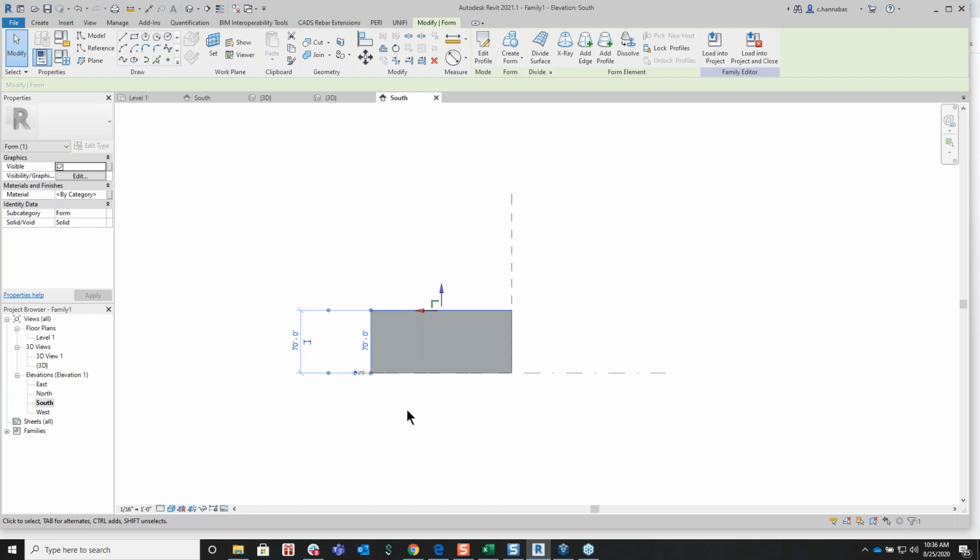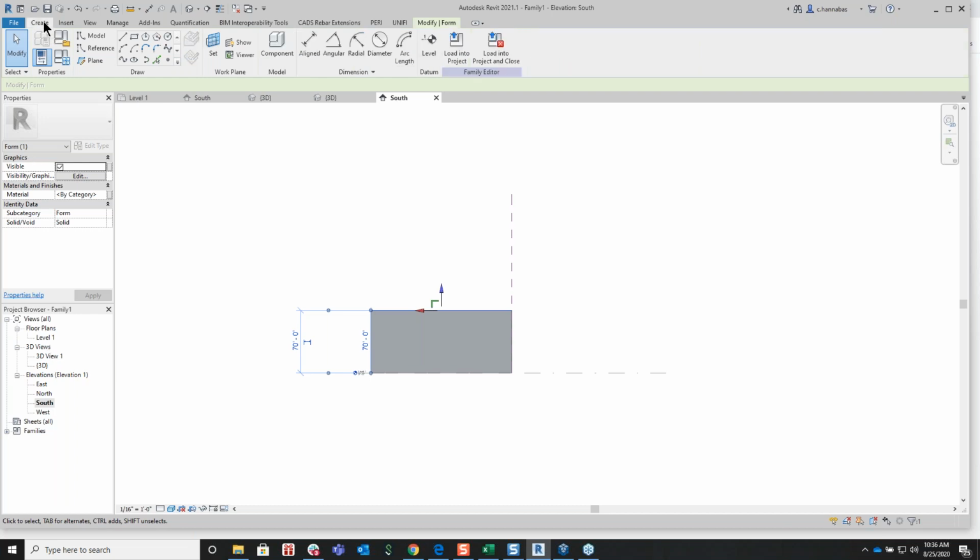and use this as my family to help generate some of the more complex buildings, especially taller buildings like you're talking about, where you may go from a large rectangle to a smaller rectangle to a smaller one, and you would just build it up through here using this adaptive component for a mass. And you can also create very complex curtain walls.